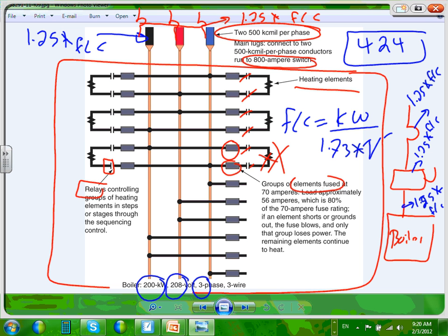Any question? That's all we need. Now, what's my requirement, Phil? When they come to me, what do they want us to do? Everything inside the red box that I drew is not your responsibility. You bring a cable to it, a disconnect next to it within sight, or capable of being locked in the open position somewhere else, and a fuse or a circuit breaker. Done. How do you size the fuse or circuit breaker, the disconnect, and the cable? You can see it right in there.